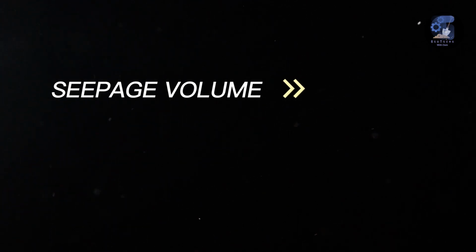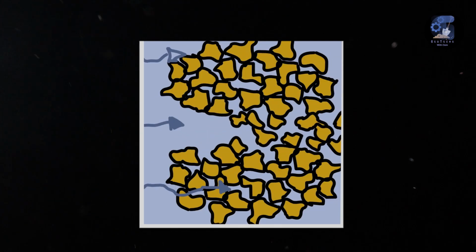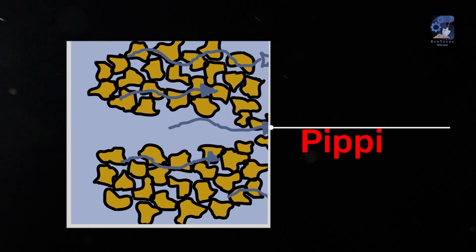One pertains to the volume of seepage, and the other is concerned with the forces exerted by seepage flow. The forces exerted by water as it flows through the foundation can cause an effective reduction in the weight of the soil at the toe of the dam and result in the lifting of the soil. If uncontrolled, these seepage forces can cause a progressive erosion of the foundation, often referred to as piping, and allow a sudden collapse of the structure.